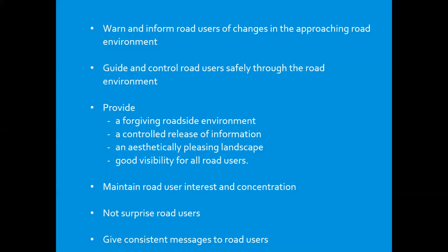Various research studies have shown that the number of accidents increases as the number of decisions required by the driver increases. Standardization of road design features and traffic control devices plays an important role in reducing the number of required decisions, as the driver becomes aware of what to expect on a certain type of road and what to expect in the urban environment.